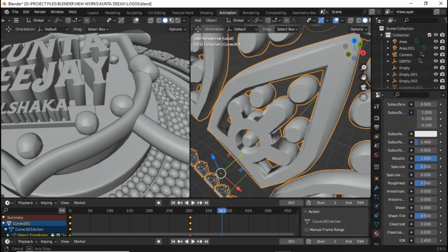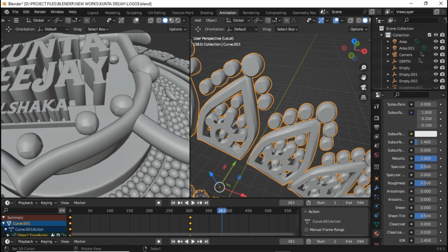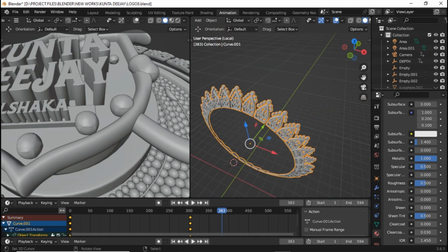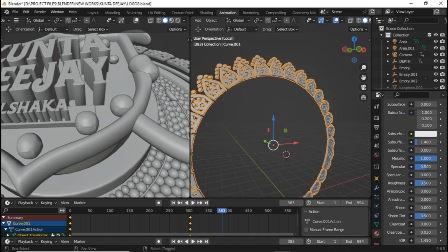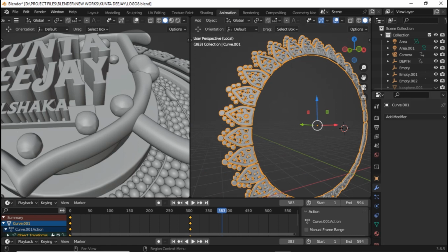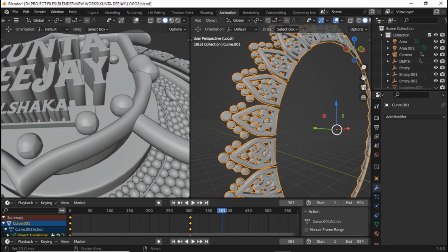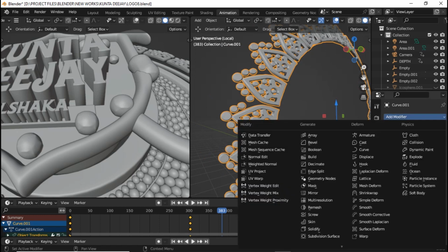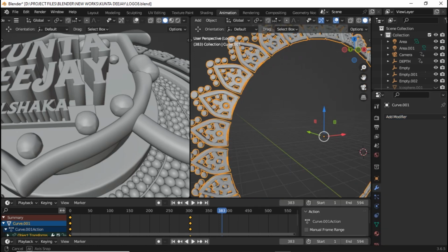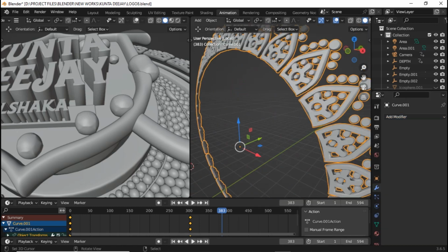You see it's kind of a simple mesh with some subdivision surface, and I created a circle and added a mesh deformer, but so far I applied them, so you cannot see. I used an array modifier, then I hooked it onto the curve. That's why you see it's a round mesh.